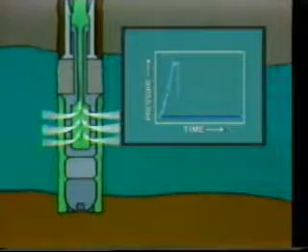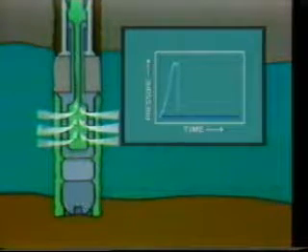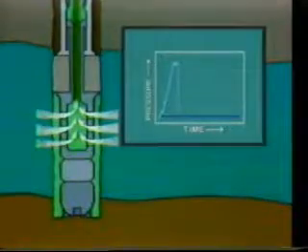If we need more information to determine if our well merits completion, we can go one step further and cut a conventional core by stopping drilling just before the anticipated producing zone and replacing the bit with a core bit and barrel, which cuts a cylindrical core of rock from the formation and allows us to view it directly at the surface. We might also carry out a drill stem test, where we temporarily isolate the productive zone and allow it to flow, letting us see firsthand its productive capacity and fluid contents.